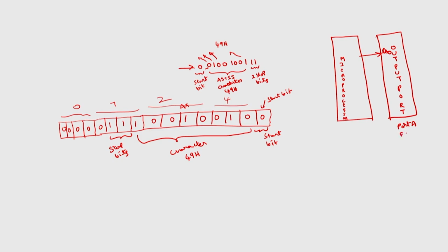First I have to program port A as output port. So, let us say the address of port A is FCH, then the control register will be FFH. To program all the ports as output ports, we know the control register, so we will do OUT FFH, which is the address of the control register, comma AL. With these two instructions, this will program all the ports of 8255 in mode 0 as output ports.